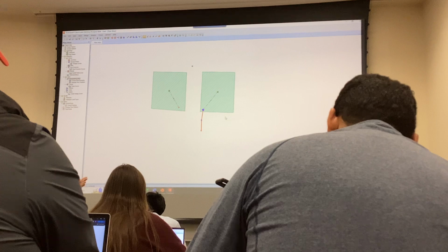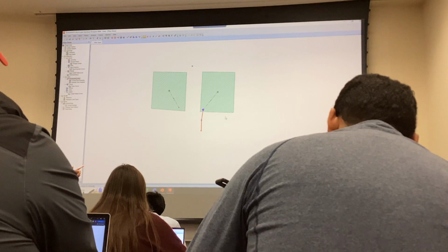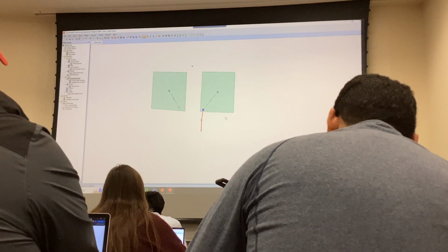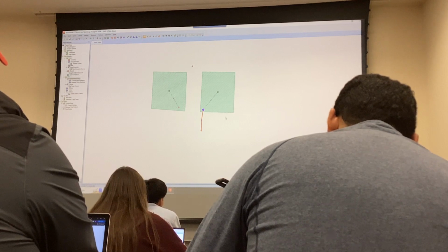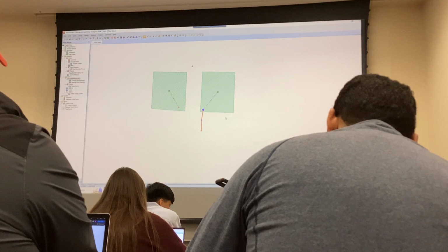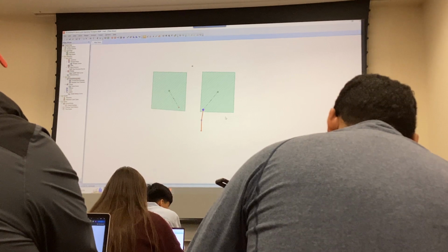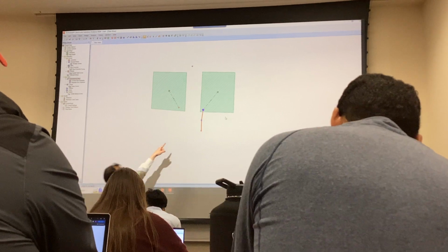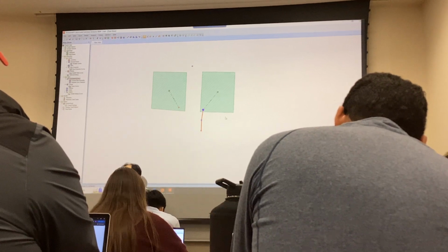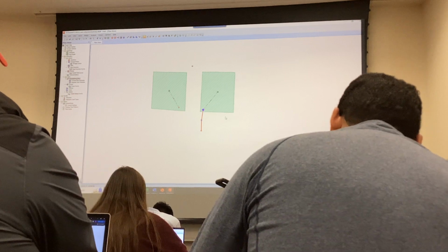If you look at my model, that blue dot pops up, and then the red line basically pops up, right? That basically tells me that, first of all, the red line has a length. That means I have pressurized flow, which is not good. And the blue area means that you have surcharge. Now, sometimes the blue dot appears on your detention basin itself, which means that you're overloading your detention basin.